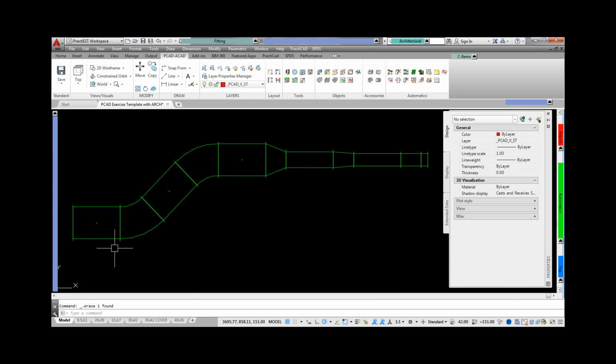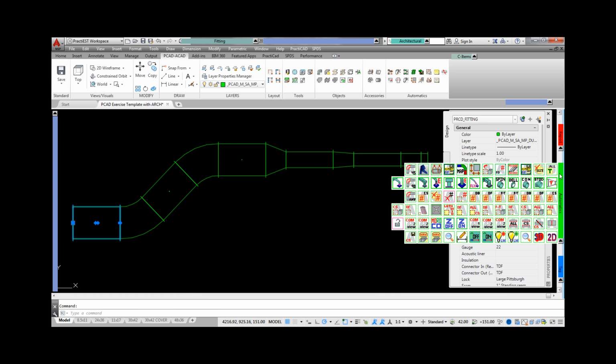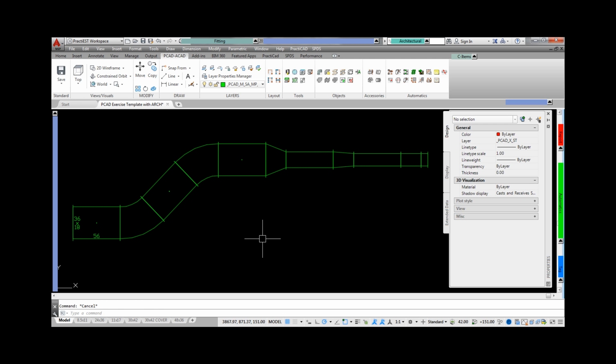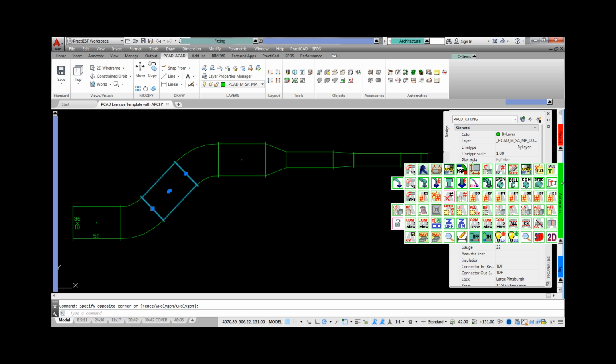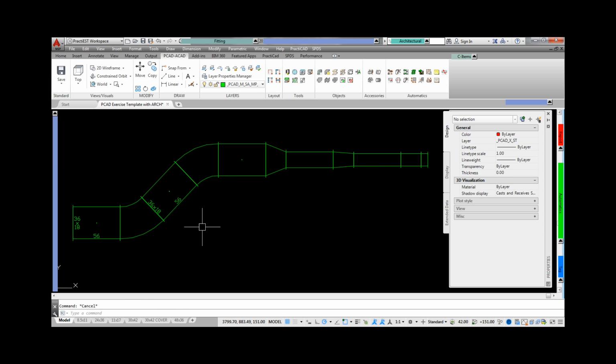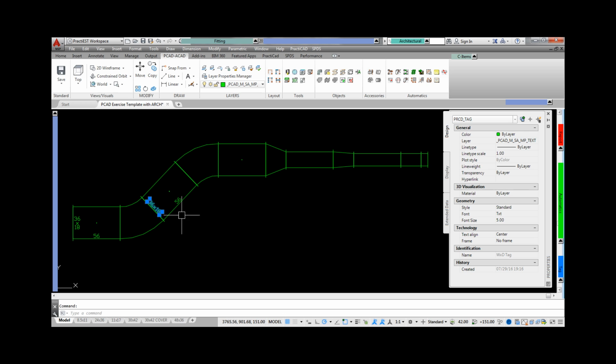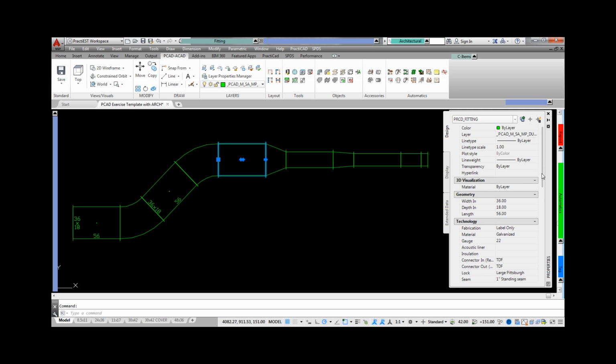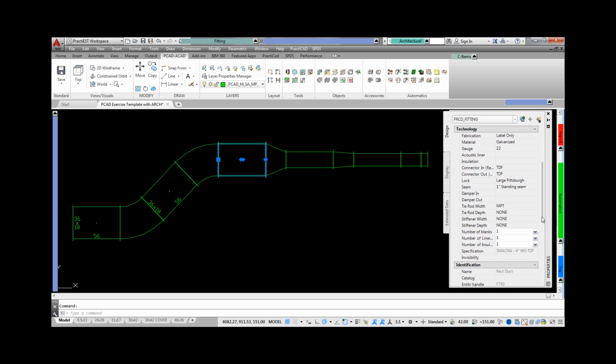The second most important part about PractiCAD's advanced auto tagging is positioning. Watch carefully as we auto tag a piece of duct running left to right on the drawing and show the name of the tag in the AutoCAD property box. Then we tag a duct running up at an angle to the drawing. Looking at the property box again, you can see we get two different tags here because of two different orientations. PractiCAD can use virtually any variable, including orientation, to make sure a tag goes exactly where it should, anywhere on the X, Y, or Z axes.